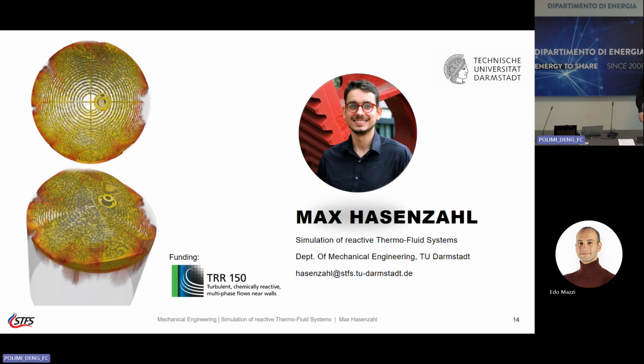I think the comment is very important, because what we need to stress is that we're all used, from our fluid mechanics courses, to looking at it in y plus, u plus dimensions. What we really have to compare in an engine flow is the absolute numbers. Really, the velocity over real wall distance. But then we have to come back again to check our picture. Do we have adverse or favorable pressure gradients? We have to go non-dimensional at some point.